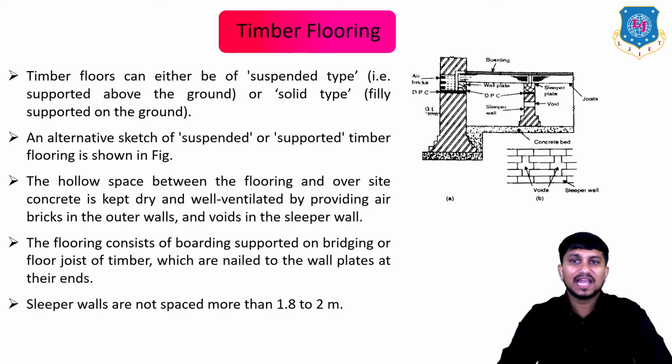These timber floors can either be a suspended type of floor or solid type of floor. An alternative sketch of suspended or supported timber floor is shown in this figure. You can clearly see the hollow space between the flooring and over-site concrete is kept dry and well ventilated by providing air bricks in outer walls and voids in the sleeper wall.